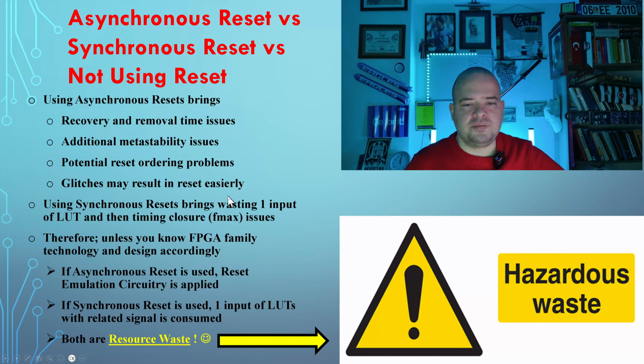Then that 30 picosecond signal may result in asynchronously resetting all your logic. This would be a huge problem. So noise, EMI/EMC problems, digital interferences, and RF interferences may result in your circuits, your logic, your processes being reset.